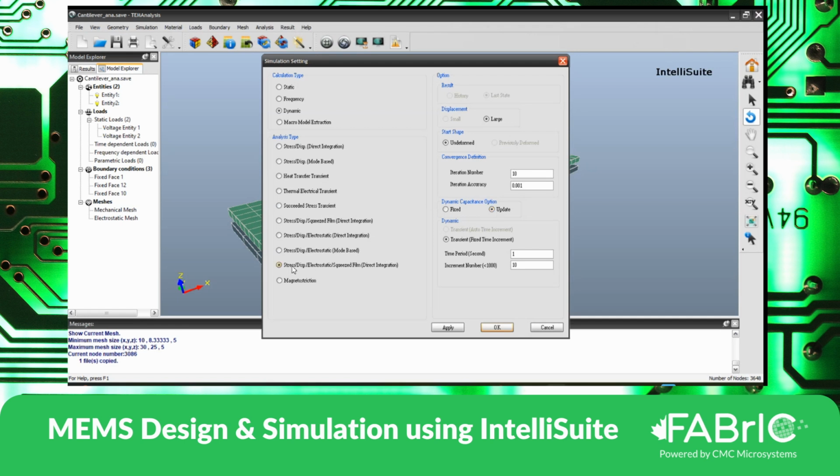The last second option of the physics, stress displacement electrostatic squeezed film, is specific to electrostatic based devices where a potential difference is applied. In the case of stress displacement squeezed film, it's purely a mechanical simulation where we define the material properties, and due to pressure, force, acceleration, loads, the simulation takes the input and corresponding outputs are thrown out.